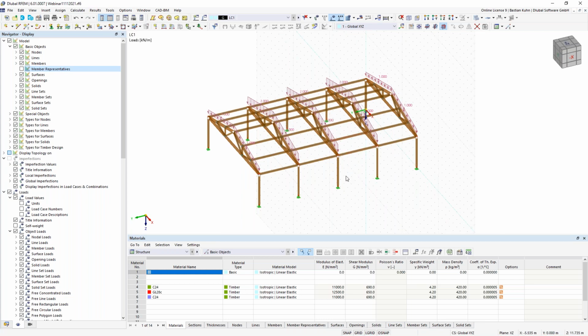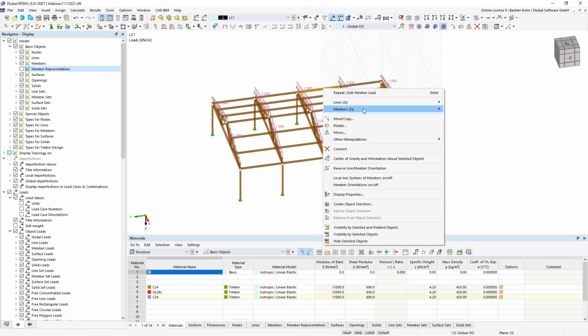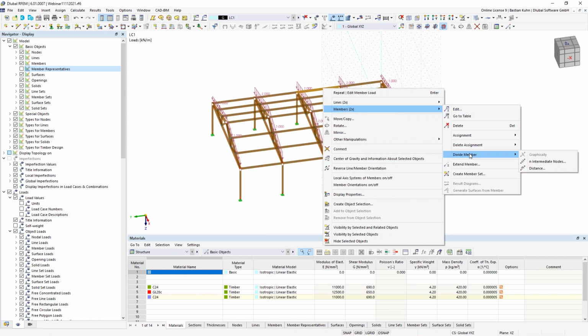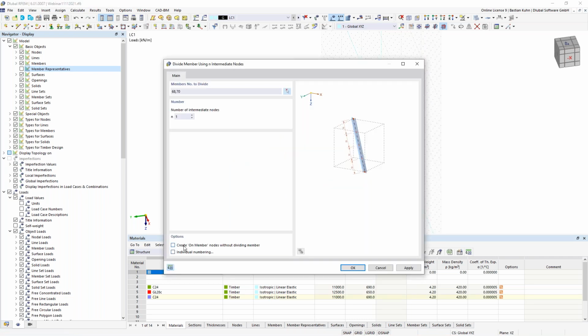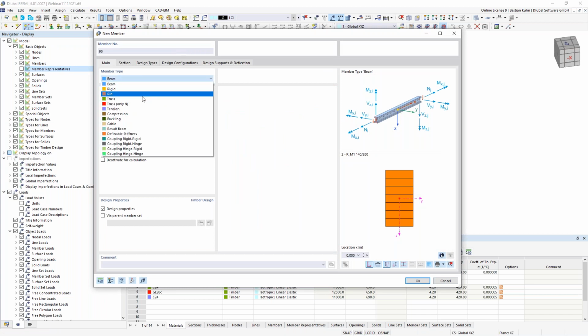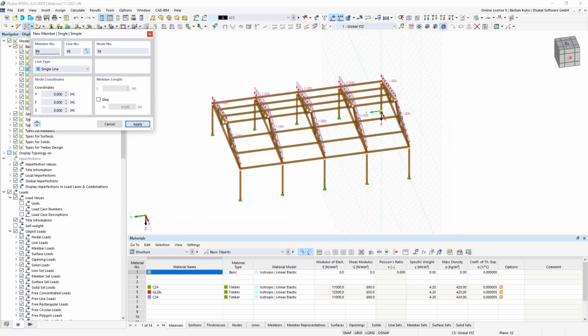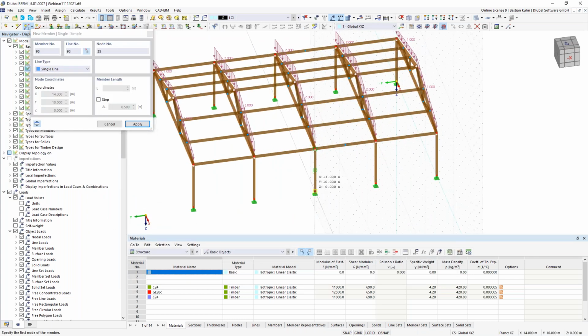And now we need to define there also stiffening elements. I choose to define my stiffening elements near the middle of the structure, because it makes the most sense to me. Once again, divide the member by 1 node and without dividing the member, and define the section there. And I'm once again choosing the truss and the section 14 by 14. Okay, oops, here as well, tick, and here. So now the walls are stiffened out into the Y direction.